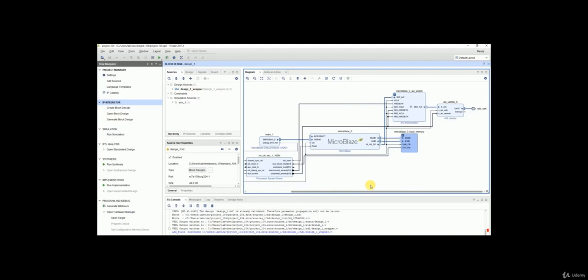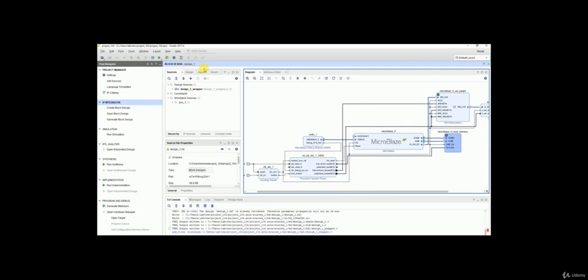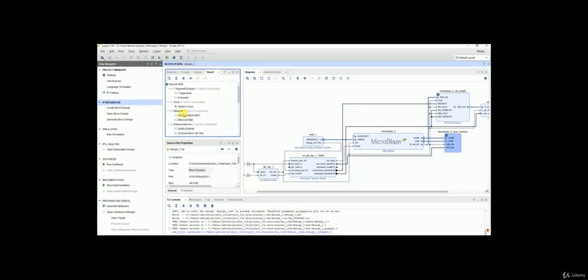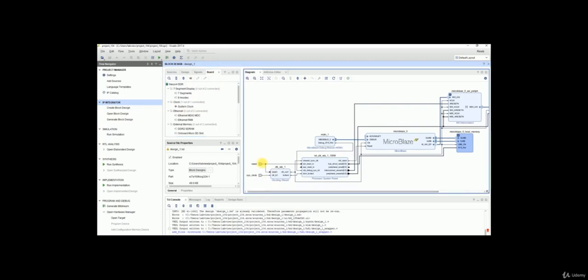Since we have utilized all the peripherals which are identified by default by Vivado, we do not need to add a constraint. Once we add our own peripheral IPs, there we need to add ports. In that case, we need to perform intermediate steps, that is, we perform synthesis, implementation and so forth, right?